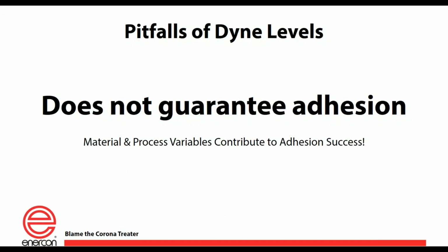For any of you folks out there that have had experience with or suspect backside treatment issues, and you're trying to figure out if that actually happens, or you're in the middle of that and you have a concern, flip a sample over, take the side you suspect to have backside treatment, and if you know the inherent Dyne level of that material is supposed to be, say, 30 dynes, take some 32 or 34 Dyne and a Meyer rod and spread it out on the back of that sheet. And if there's backside treatment back there of that sufficient amount, you will see a pattern show up. That pattern can then direct you to maybe a cause to remedy that problem.